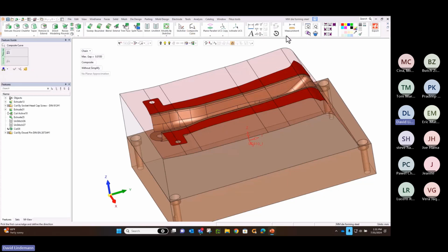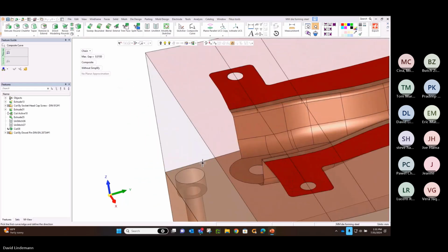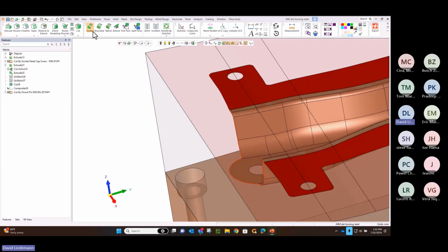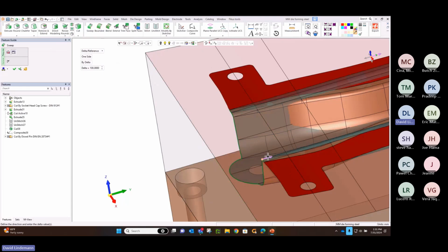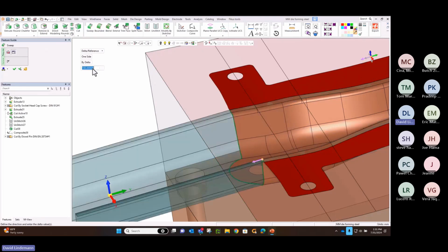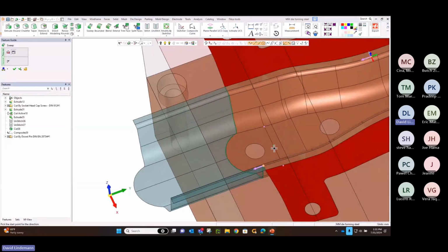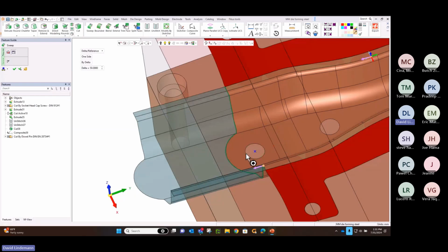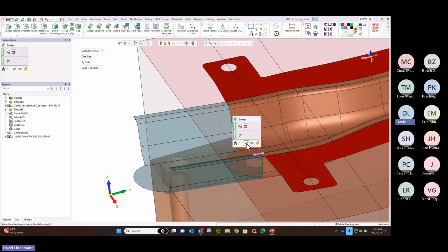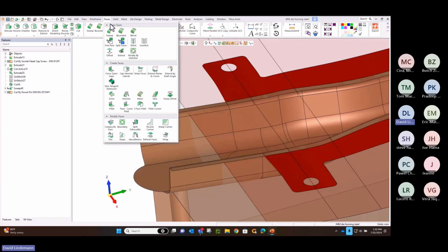I need to open that up where I've got the trench, right? That groove. So I'm just going to say I want to create a chain from one side to the other. And then I'm going to direct that out into some faces, and we'll give it a respectable distance. And I'm going to say follow the slope that it's got based upon the bottom here. So I'll get to the midpoint and then go through the center point here of that hole. And that's directed it at that same sloping direction.